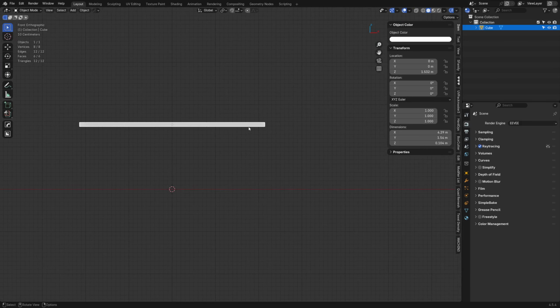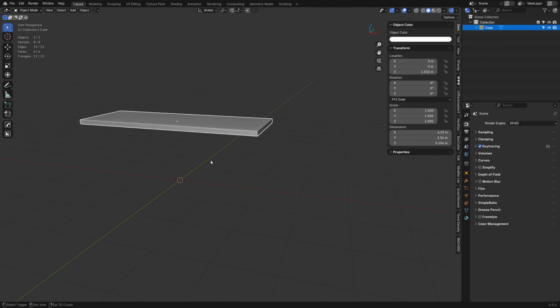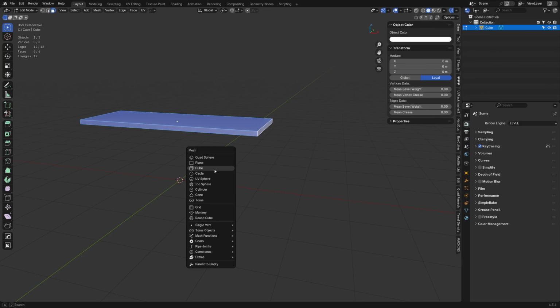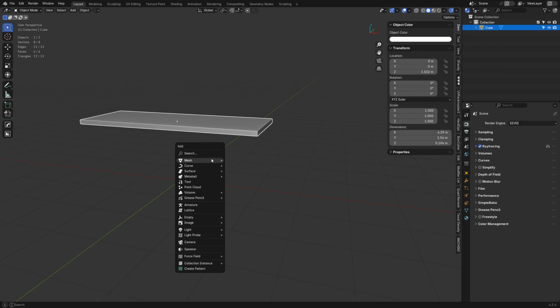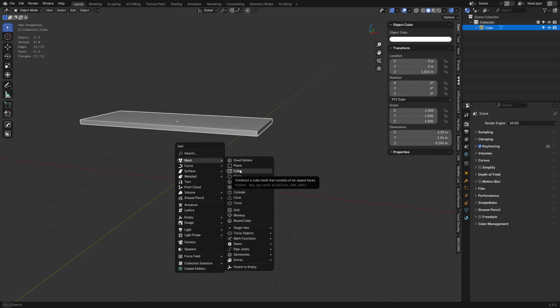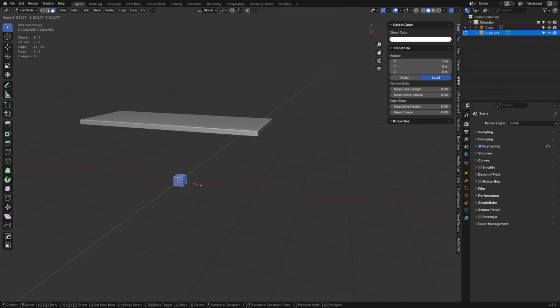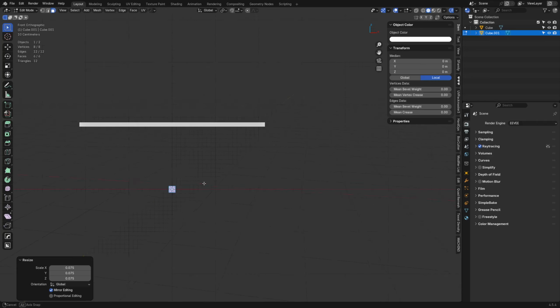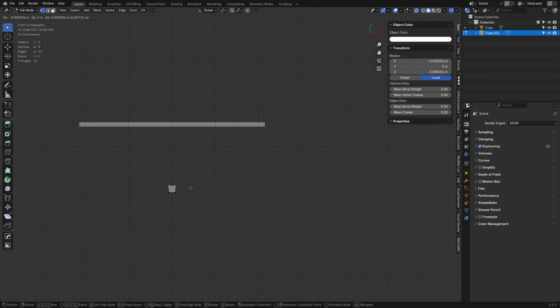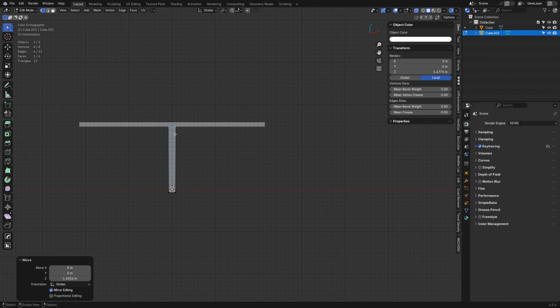And let's go ahead and press Shift A in object mode. If you're in edit mode and you hit Shift A, you'll create new objects within this object. So be careful: Shift A in object mode. Create cube. Go into edit mode. Scale uniformly all the way down until we get kind of a square shape. Select by vertex. Alt Z. Press GZ. We're going to line these up by eye.